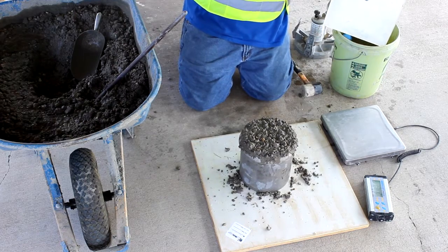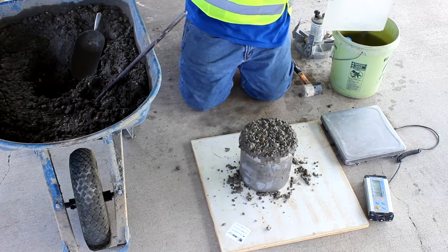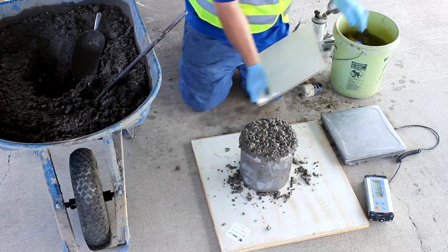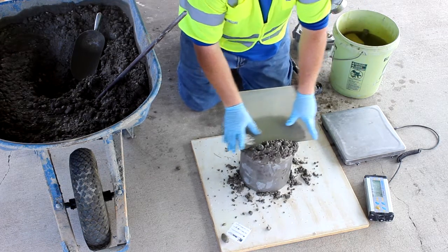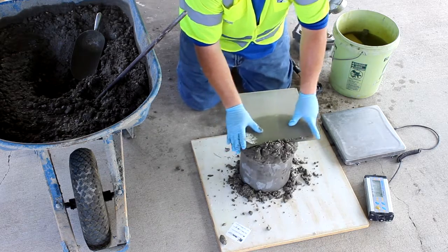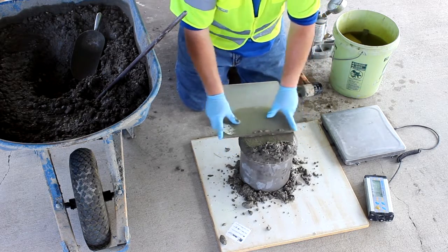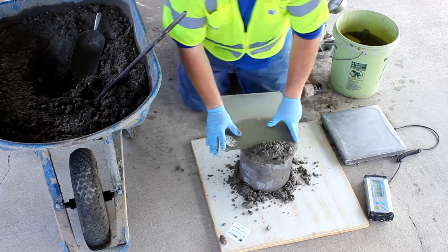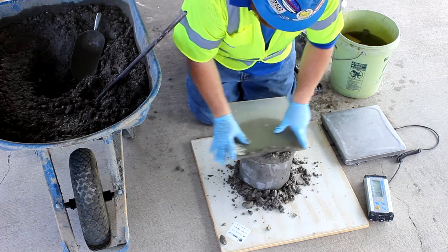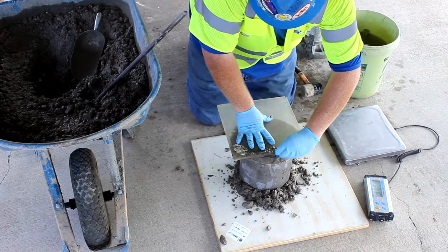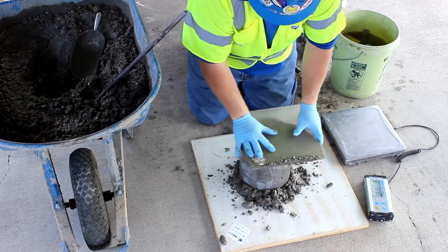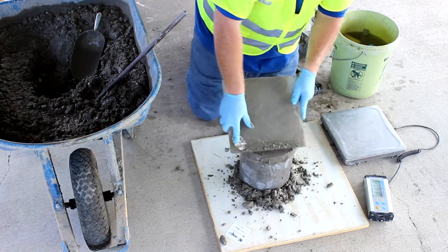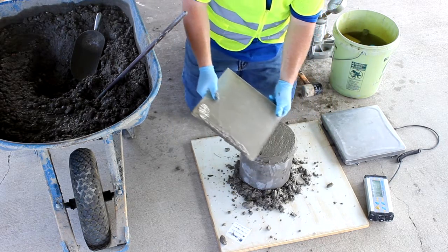Strike off the top surface of the concrete and finish it smoothly with the flat strike-off plate, leaving the measure level full. Press the strike-off plate on the top surface of the measure to cover 2/3 of the surface. Withdraw the plate with a sawing motion to finish only the area originally covered. Place the plate on top of the measure to cover the original 2/3 of the surface. Advance it with a vertical pressure and a sawing motion to cover the whole surface of the measure. Continue to advance the plate until it slides completely off the measure. Incline the plate and perform several strokes with the edge of the full measure to achieve a smooth and level surface.